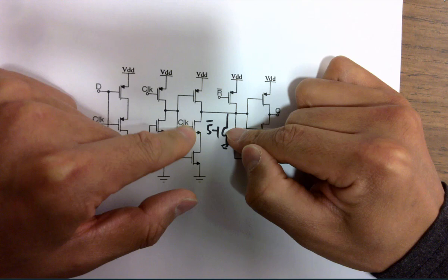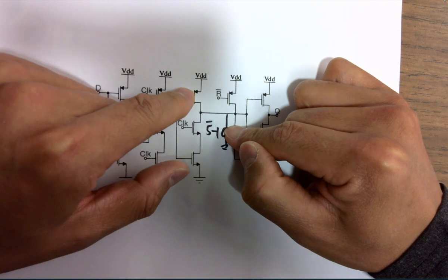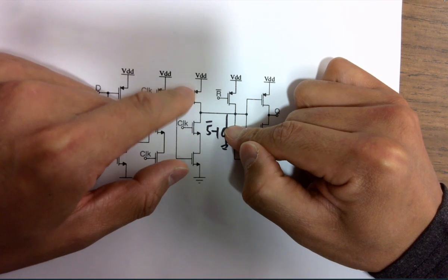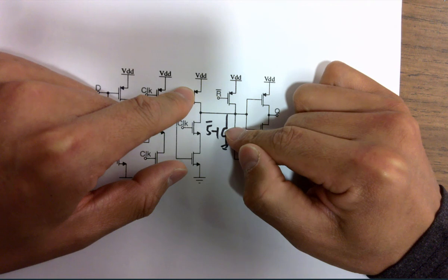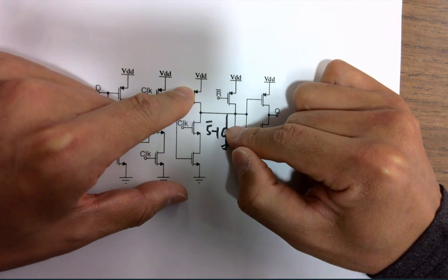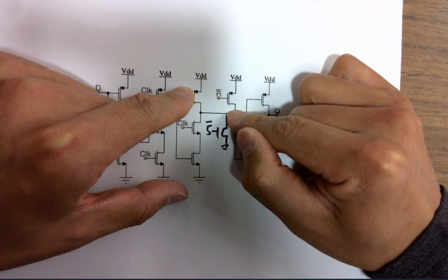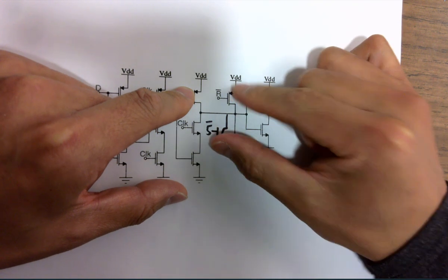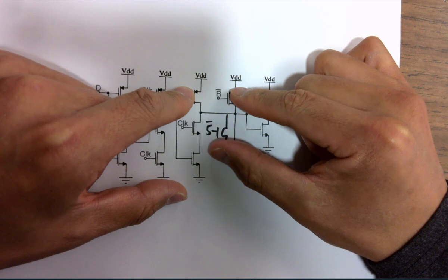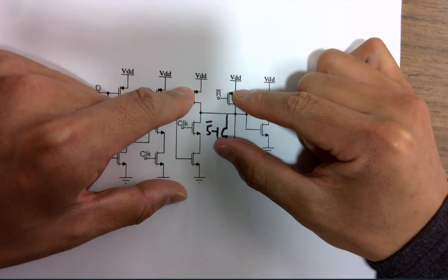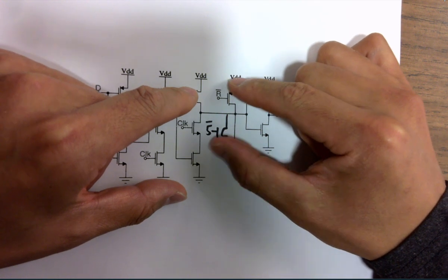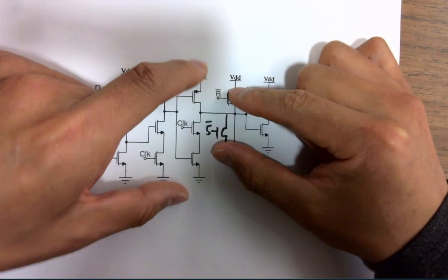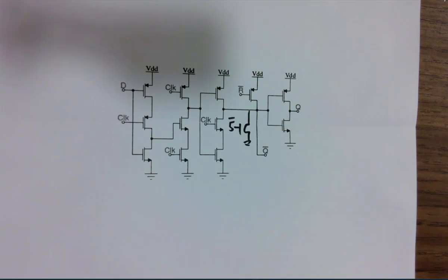And same for the NMOS, right? So this NMOS is probably competing with this PMOS at the moment, right? So just make this NMOS super big, super wide, so whenever it's pulling it down, it's able to pull it down. So you are not setting a resistance at the same time because both are strong, and that will be a pretty weird situation. But you are not turning on both at the same time anyway. So that's about setting and resetting. Pretty straightforward compared to the previous one, right? It's basically just pulling up and pulling down.